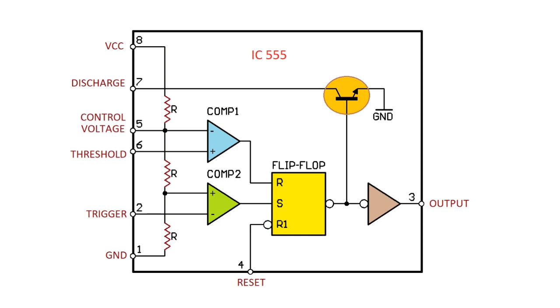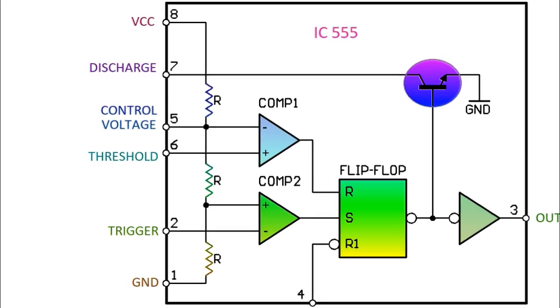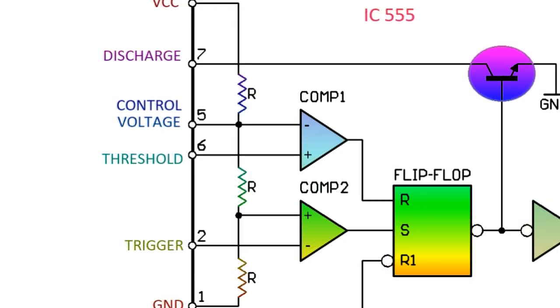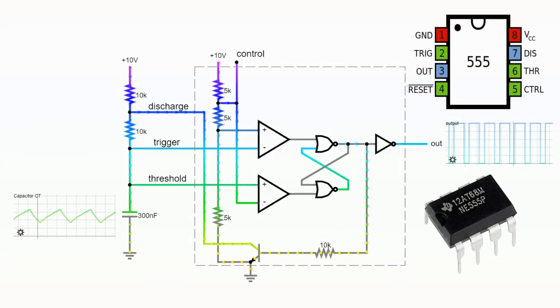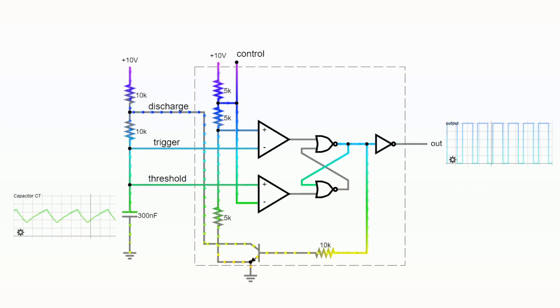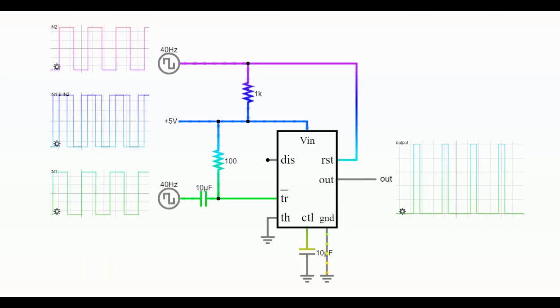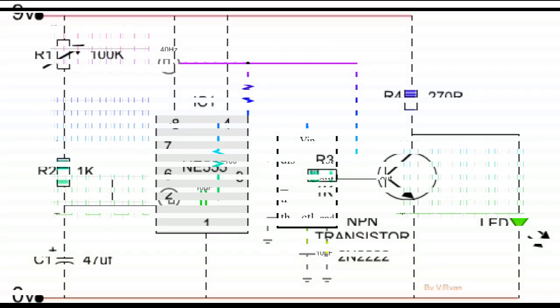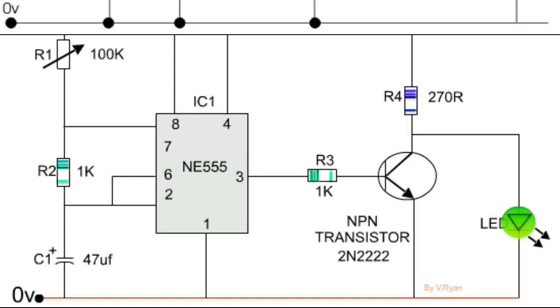The basic 555 timer gets its name from the fact that there are 3 internally connected 5K resistors which it uses to generate the 2 comparators' reference voltages. The 555 timer IC is a very cheap, popular, and useful precision timing device which can act as either a simple timer to generate single pulses or long time delays, or as a relaxation oscillator producing a string of stabilized waveforms of varying duty cycles from 50 to 100%.